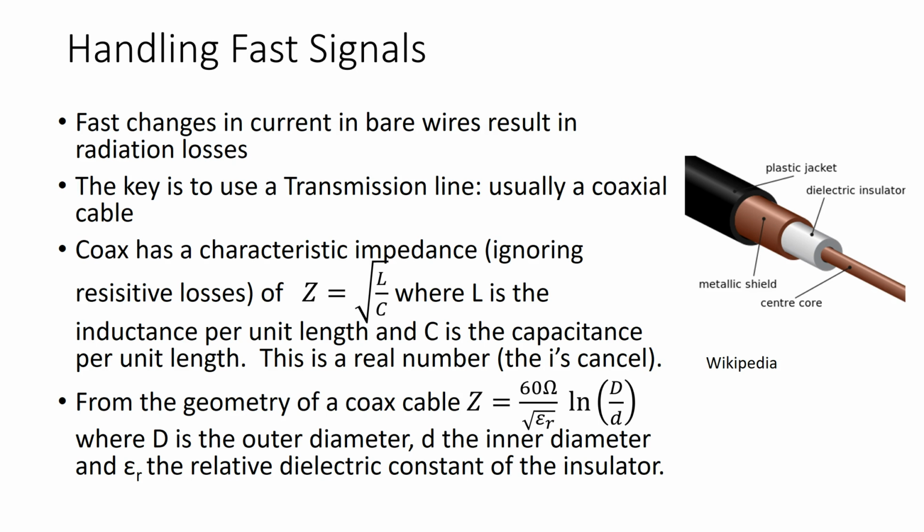So how do you communicate fast signals, either a high frequency sine wave or a pulse with a very narrow width or a very sharp rise time, which by the Fourier theorem we dealt with in the last class means high frequency components? The key is to use a transmission line. Hopefully you've had an E&M class and covered transmission lines, but these are circuits that act like lumped L and C continuously distributed, so that these things are like filters with a passband over a broad range of frequencies. They have a cutoff frequency that you can find on the specification for the transmission line.